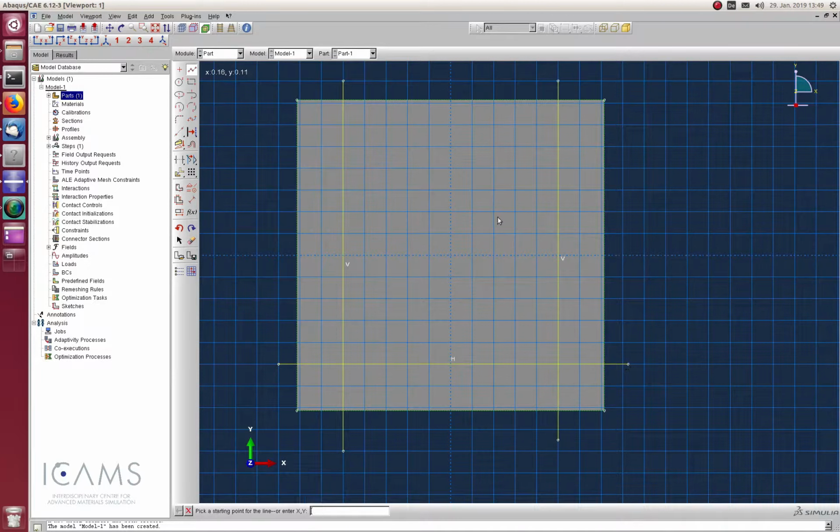And some horizontal lines. These will give us the point of intersection. To find the intersection point for creation of geometry, generate some more lines in the horizontal and vertical directions as shown. Now again, select the Add Dimensions tab and give dimensions of 0.25 to the lines from the top, bottom, left and right to the newly generated lines.